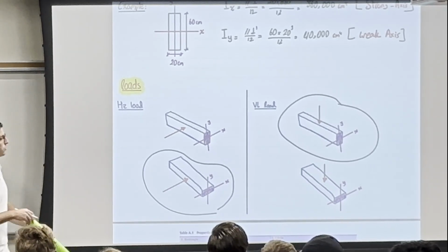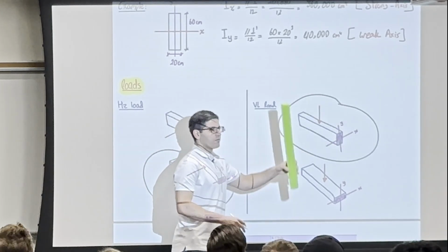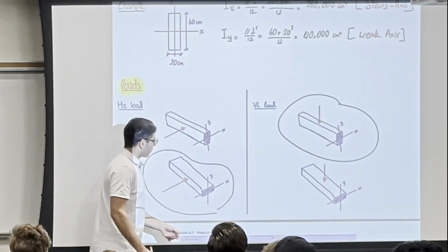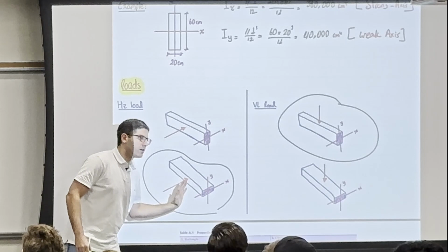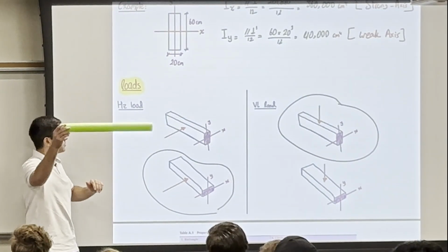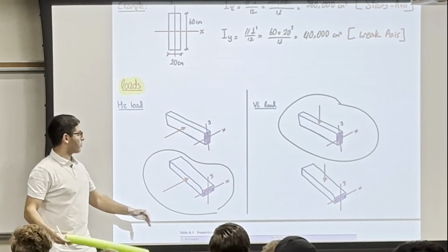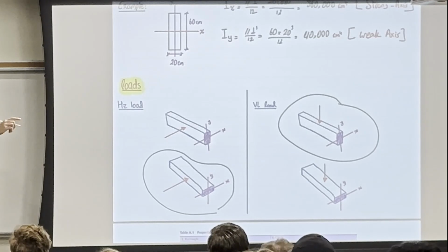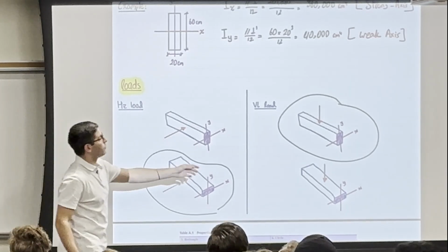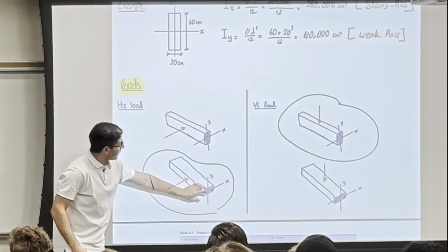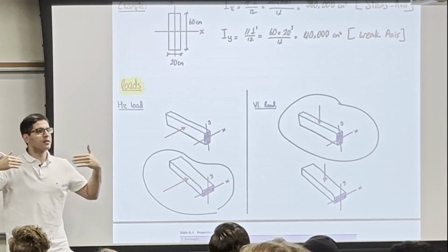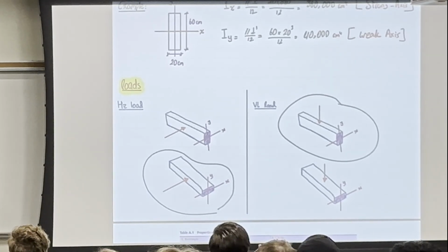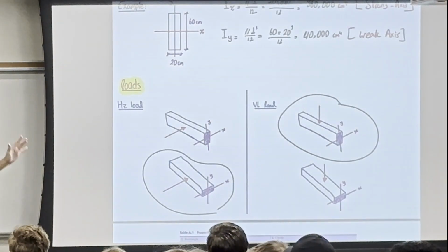If I have a gravity load, meaning us as humans and the dead load, you want to place your beam like this. But from the outside, you have wind. So for the outer beams, at some point on the outside of your building, you want to place them that way. Whoever went to the gym, you'll not find all the beams at the wall looking like this. Some of them look like this. It's placed that way so that it can resist the wind coming on the building, especially since we have a very big facade at the gym. So imagine all this wind pressure in that area.